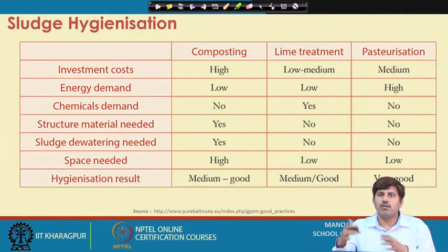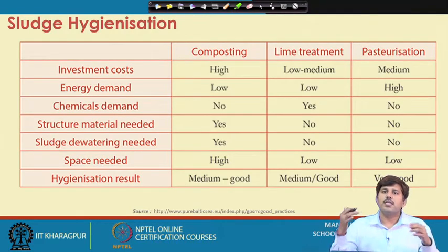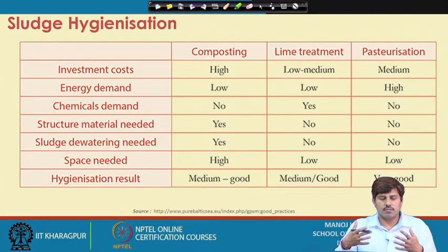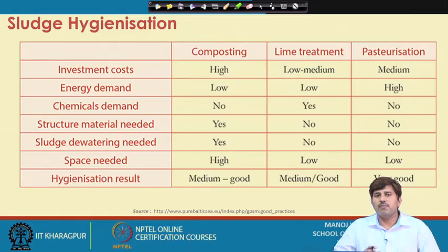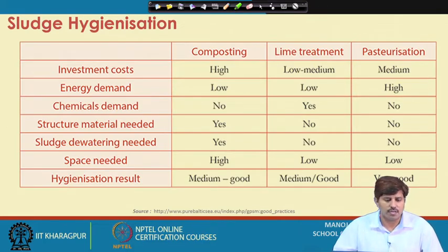In the form of sawdust or something similar, we can mix it into the sludge, and then we put it for composting. Aerobic composting in the presence of air and the desired level of mixing will produce compost in a span of say 30 to 60 days typically. At times it may take longer depending on such characteristics.